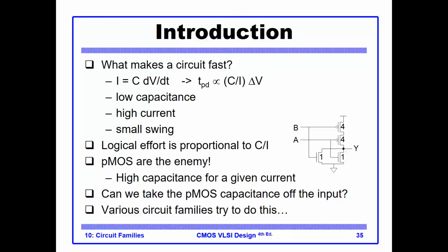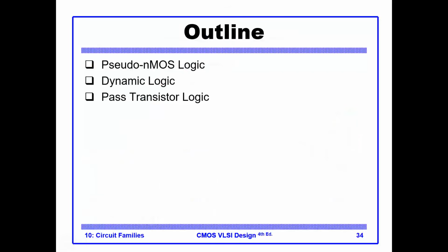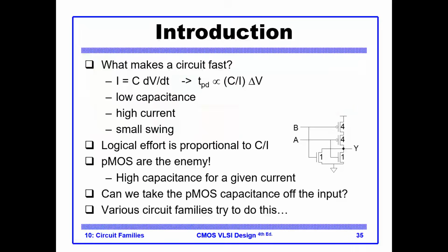As we said, what we're trying to do here is that we don't like, in complex CMOS, these stacks of PMOS. PMOS tend to be weak. They have weaker mobility compared to NMOS. They tend to be slow, in particular when they are stacked, and they have a large load on the driving gate. So it's good that we can get rid of them, and we're trying to get rid of them in this lecture.